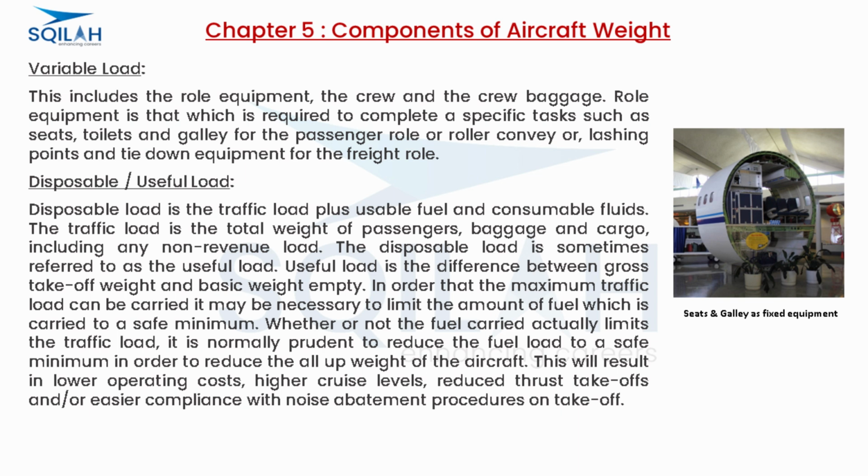Disposable or useful load. Disposable load is the traffic load plus usable fuel and consumable fluids. The traffic load is the total weight of passengers, baggage and cargo, including any non-revenue load. The disposable load is sometimes referred to as the useful load. Useful load is the difference between gross takeoff weight and basic weight empty.